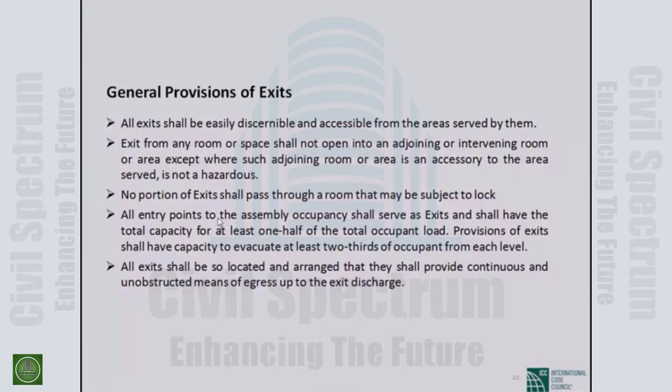No portion of the exit shall pass through a room that may be subject to lock. This happens particularly in institutions. You should be careful while designing this exit so that it should not pass through a room, and it should not be locked.